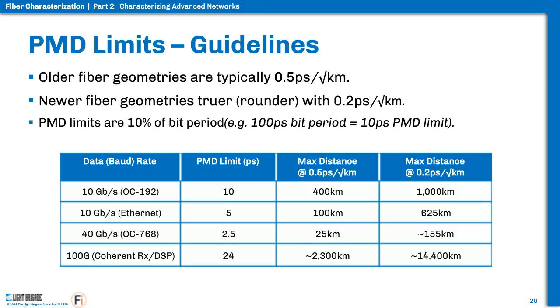Another point just to make here, this isn't something you would necessarily need to remember, but the way PMD limits are defined, it's 10% of the bit period. You can see the example here, a 100 picosecond bit period is 10 picoseconds in terms of your PMD limit.